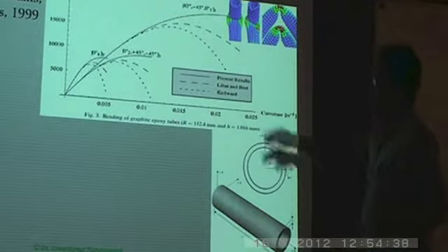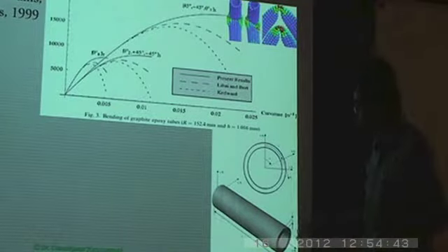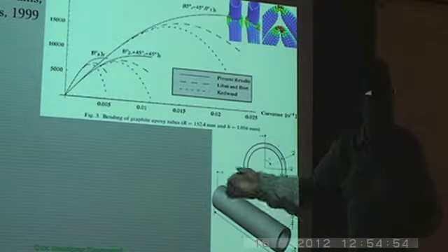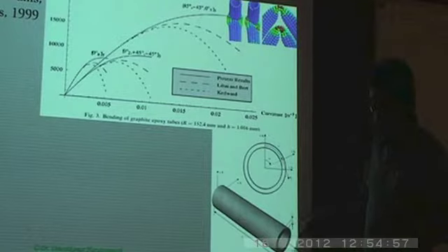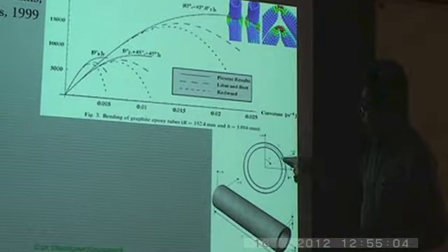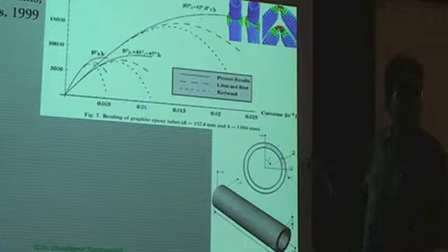So now let's look at that, part of which I've already talked about, but in a more formal sense. So basically you have a circular tube. The way you deal with this problem is you first introduce the coordinates x1 along the length of this shaft, x2 and x3 as cross-sectional coordinates. And because you can take advantage of the axis symmetry, you can introduce even another Cartesian coordinate system where you have a tangential direction and then you have a radial direction, basically circumferential, tangent and radial.